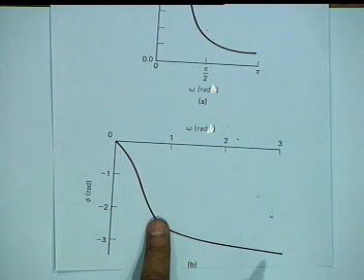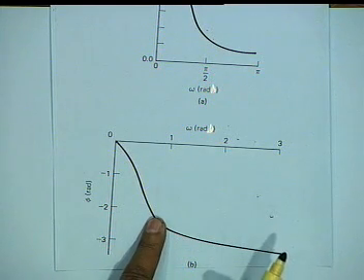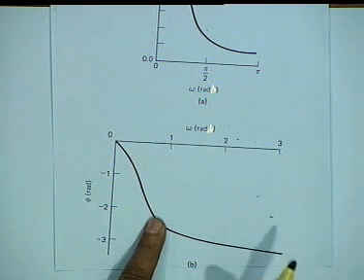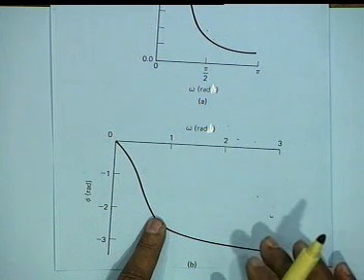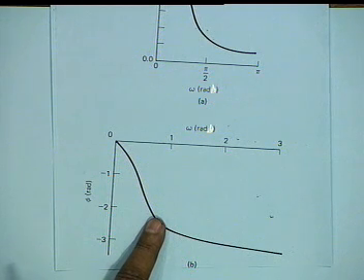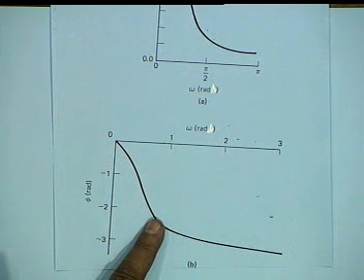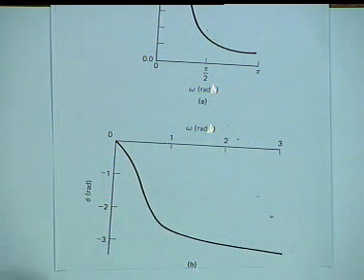As far as the phase response is concerned, there is nothing much to choose. It's again up to about 0.8, it is linear. Phase response should be checked for any design, although your emphasis is on the magnitude response. The desirable results may not be obtained because of extraordinarily large delay distortion.